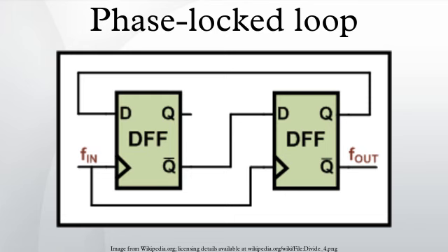PLL. Frequency synthesis. In digital wireless communication systems, PLLs are used to provide the local oscillator up conversion during transmission and down conversion during reception. In most cellular handsets, this function has been largely integrated into a single integrated circuit to reduce the cost and size of the handset. However, due to the high performance required of base station terminals, the transmission and reception circuits are built with discrete components to achieve the levels of performance required. GSM local oscillator modules are typically built with a frequency synthesizer integrated circuit and discrete resonator VCOs.